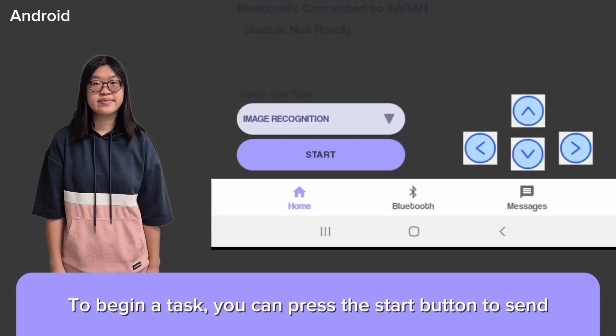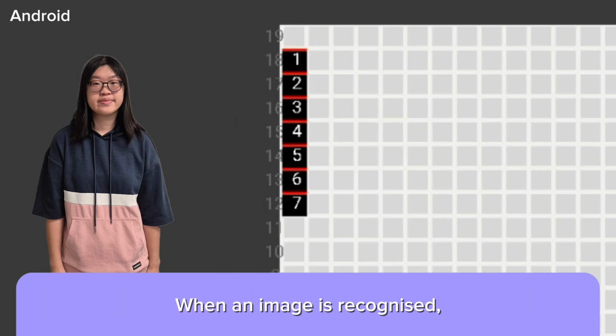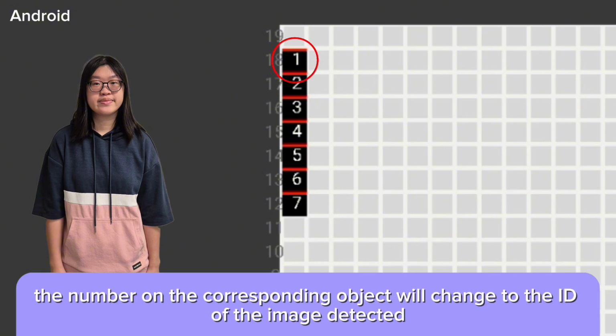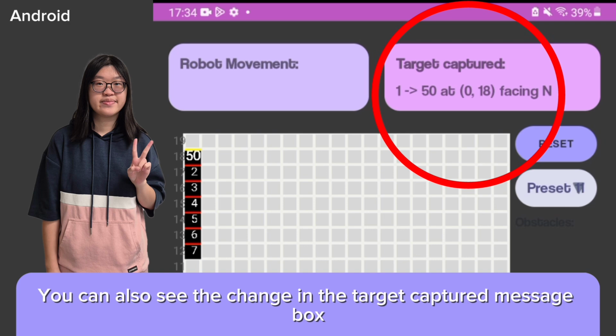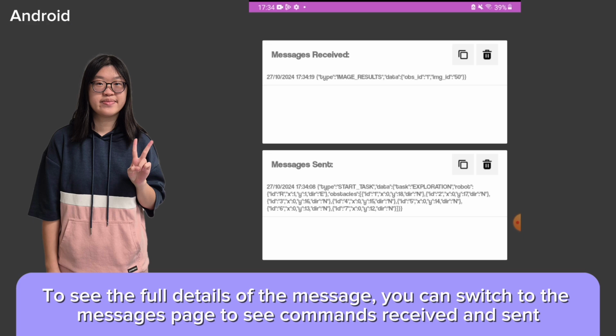To begin a task, you can press the Start button to send the coordinates of the obstacles on the map to the RPi to run the task. When an image is recognized, the number of the corresponding object will change to the ID of the image detected. You can also see the change in the target captured message box. To see the full details of the message, you can switch to the messages page to see commands received and sent.